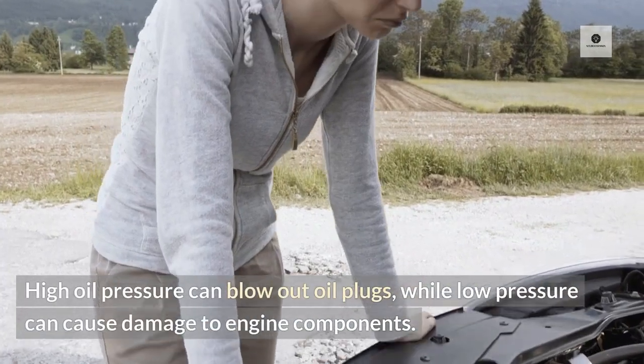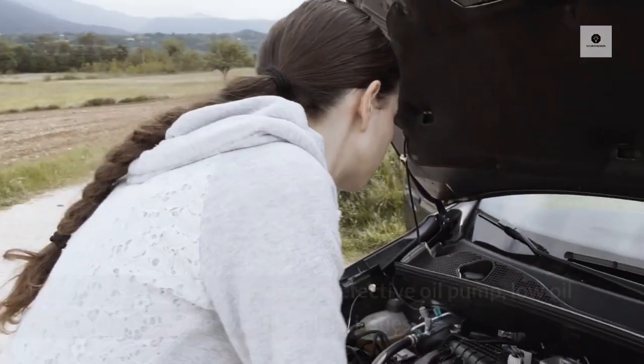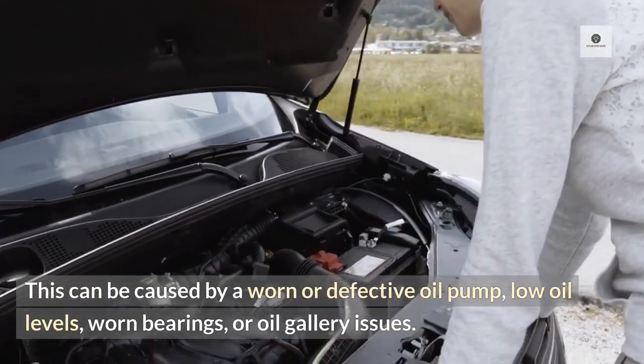High oil pressure can blow out oil plugs, while low pressure can cause damage to engine components. This can be caused by a worn or defective oil pump, low oil levels, worn bearings, or oil gallery issues.